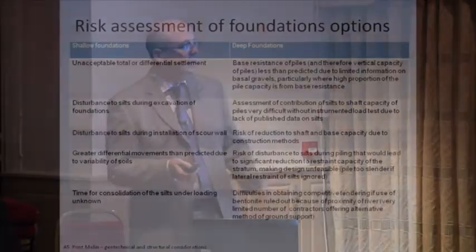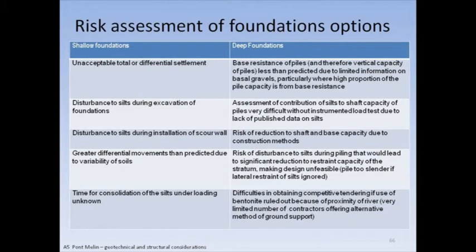So this is just, I apologise for the amount of text there, and I'm not intending obviously to read it, but what it is an indication of is the fact that, not that the risks weren't similar between the two options, between shallow foundations and deep foundations, but the complexity of risks with deep foundations and the difficulty in trying to bottom some of those issues out compared to shallow foundations were one of the reasons that took us down this route of looking into the feasibility of shallow foundations, and particularly, essentially, in order to determine that we would get the capacity from deep foundations, that we wouldn't disturb the silts, that we wouldn't cause a reduction in the lateral capacity of the silts during piling.